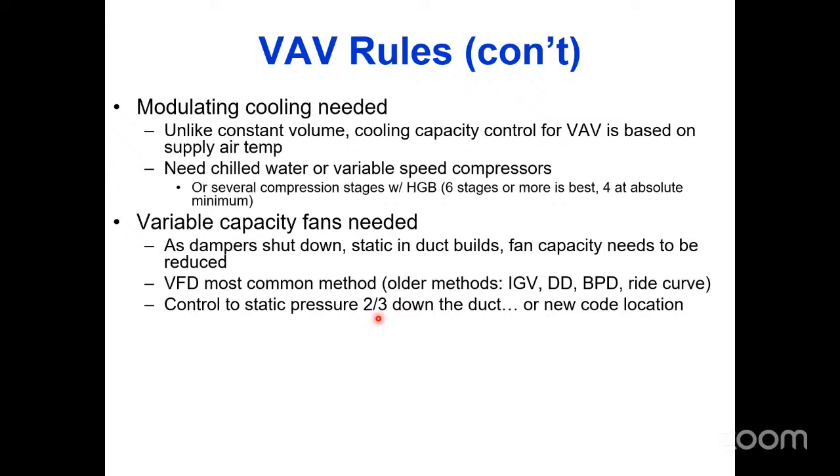The code has since changed, and I'll explain what the code requires today, but you're no longer allowed to put it 2/3 down the duct, and you're also no longer allowed to put it at the discharge of the fan. There's a new spot you got to put it, and I will explain that. But for concept, 2/3 down the duct.